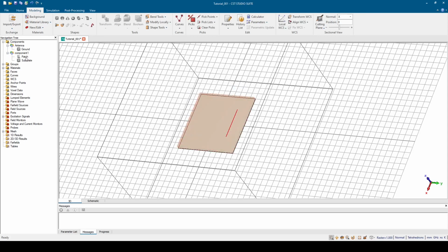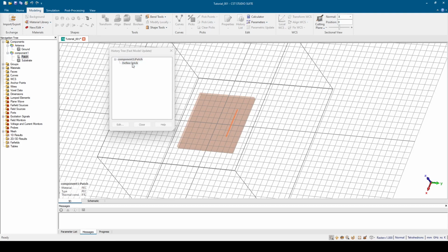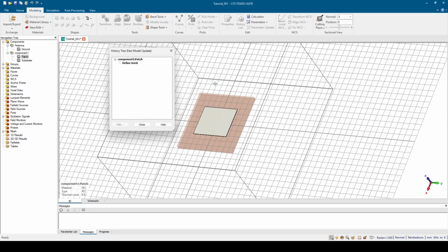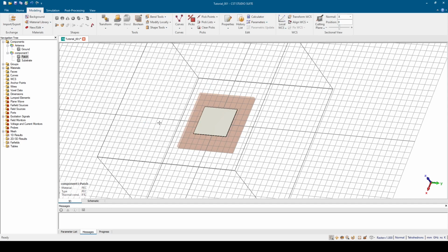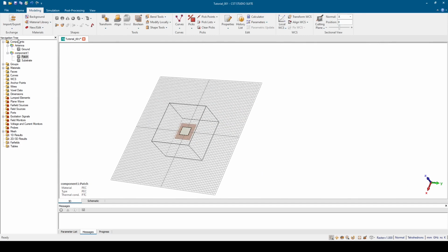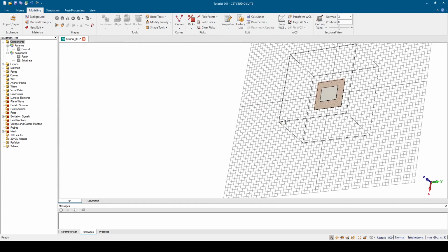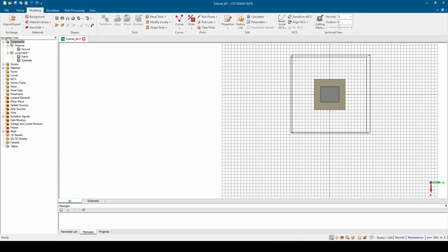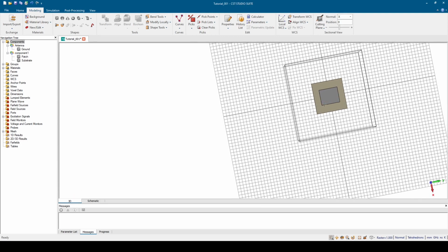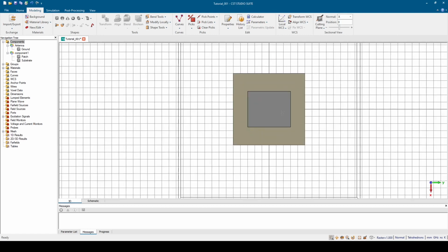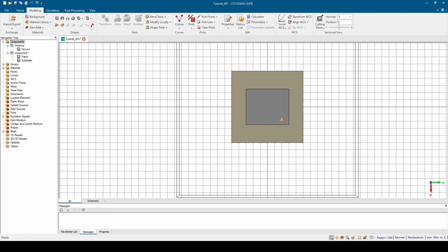Again, what's wrong here? Then go to the patch. Let's see what we did. Okay, here, yeah, I didn't do the dimension. It should be from negative to positive, so we are good to go now. So for now, this is the antenna itself. If we press 1, by the way, it gets me here directly. Press 1, just because I started to work with HFSS, so the control is a bit different.